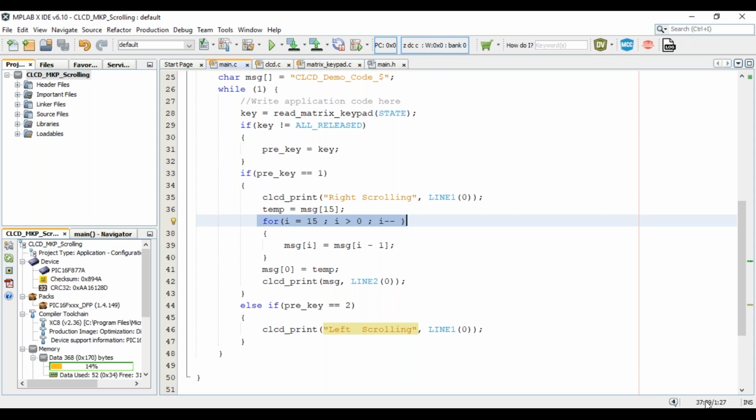Input less we can achieve with the digital keypad also. Yes, that is possible because the number of inputs are less. You can achieve with the digital keypad also. But when it comes to the digital keypad, if I'm not wrong, it uses RB pins. Now, if you're using digital keypad, you cannot choose a peripheral which needs RB, like the port B pins.